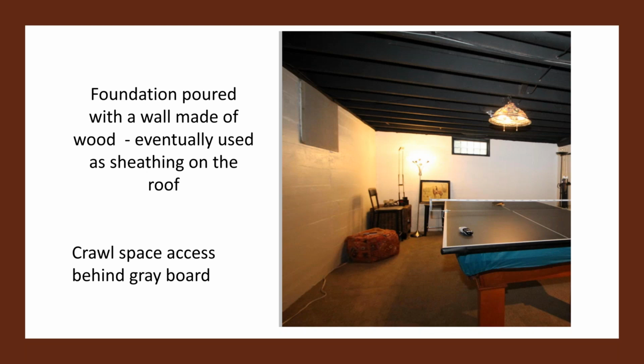And oftentimes they'll use the wood that they've used to pour the foundation to form the attic. So it could be the sheathing underneath the shingles in the attic. So when you go up into some of these older homes, and this house was built in the 50s, you will see remnants of what looks like concrete hanging off the boards up there, and that's what it's from. These boards were actually used to pour the foundation in the basement. So that would be a single form.